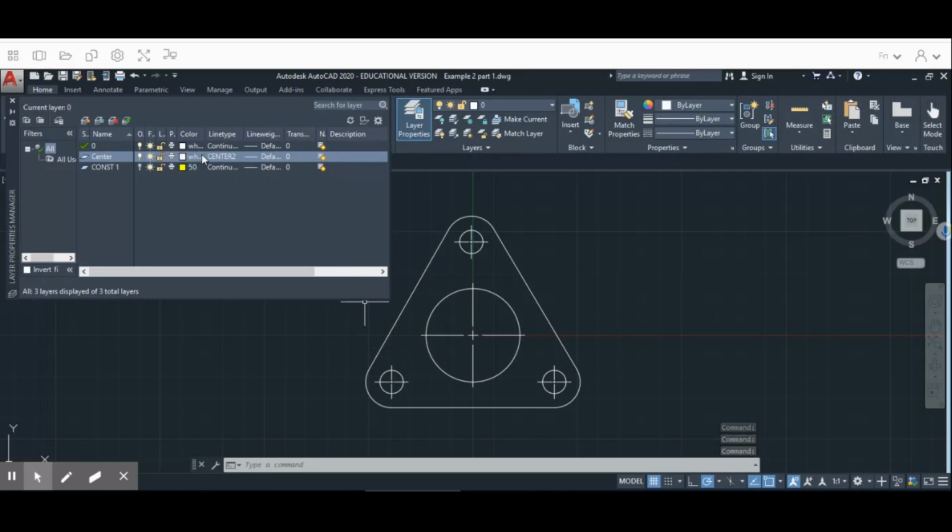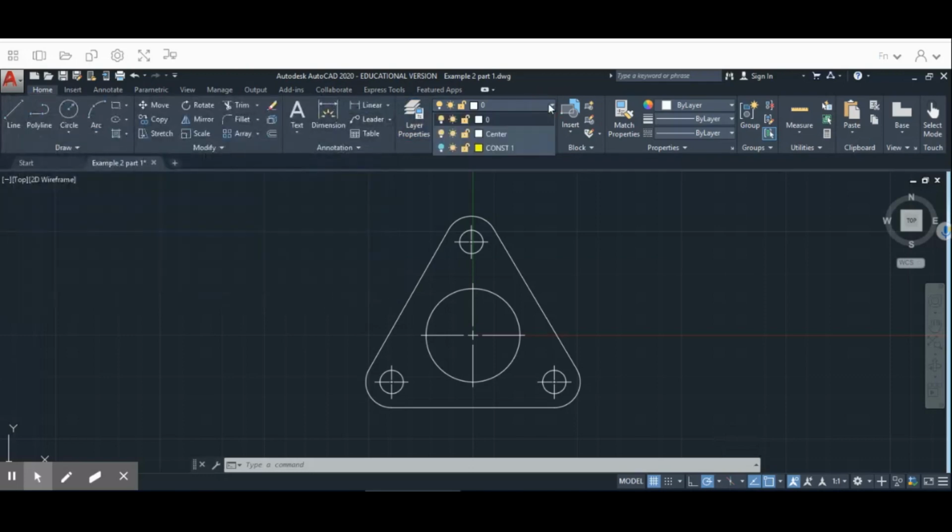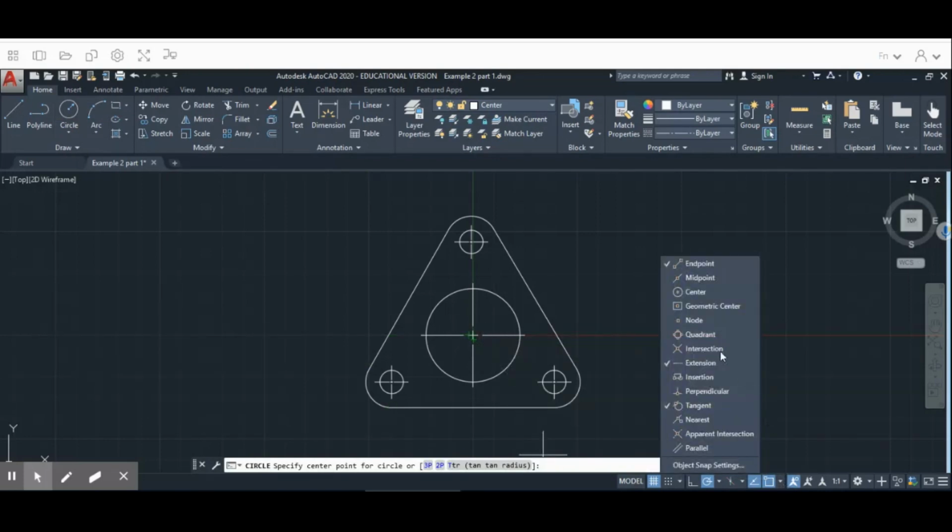So now we're going to select that center line, right? So we're going to go ahead and click out of here. We're going to select that center line, and we're going to select circle. And then from our center point here, and so let's turn on the center point again and turn off our tangents. Let's go back over here. Let's turn off the tangent. We don't need that anymore. We need to turn back on our center and turn back on our intersection.